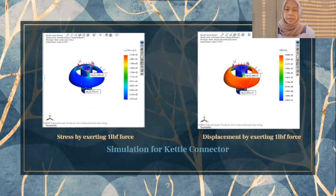Next we use is the kettle connector. For the kettle connector, same as the kettle handle, we use a load of 1 lbf, and we use 2 types, which are stress and displacement. As you can see, both don't have much difference in terms of deformation, and this is due to the von Mises stress indicator, where the maximum and the minimum are similar. Due to all of this simulation, we can use the simulation results to improve our coffee machine for better use.